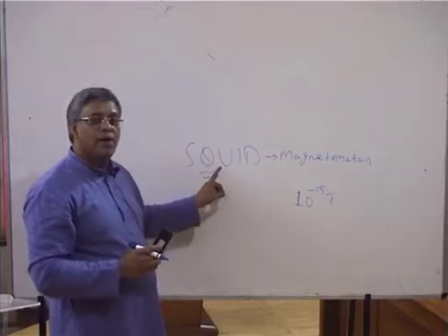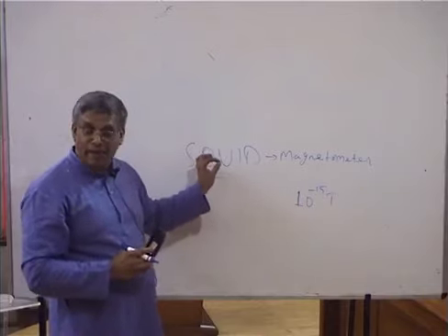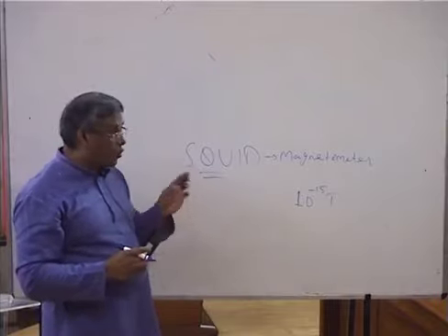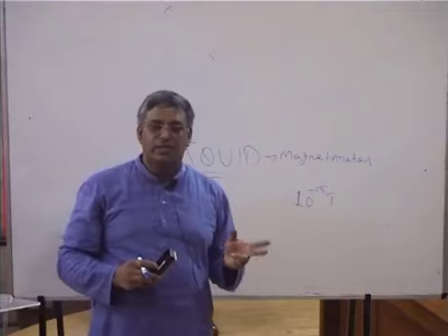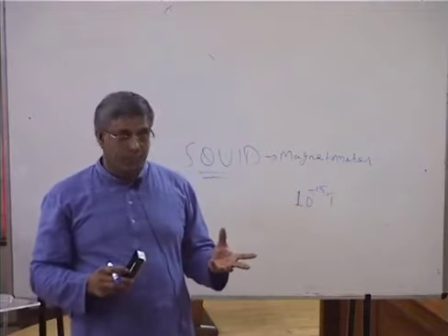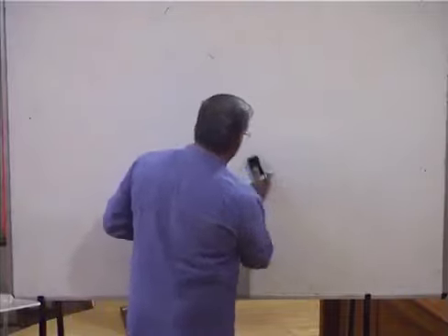You should imagine this is one of the most precise machines human hands have ever made so far. So that is the beauty of superconducting electronics. Now we have a new branch of electronics, superconducting electronics, where instead of PN junctions we have Josephson junctions. Josephson junctions replace PN junctions. And a Josephson junction, as I told you, is just a junction between two superconductors sandwiched by an insulator.